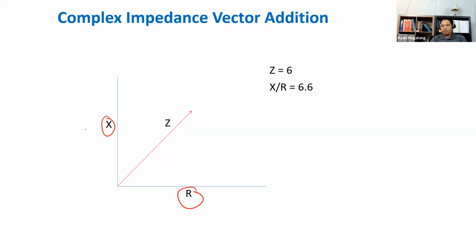And we're normally given the XR value; your transformer comes with your XR value. The transformer nameplate itself would show that. What else? Your utility, like I said, really try to get the actual XR value from your utility.